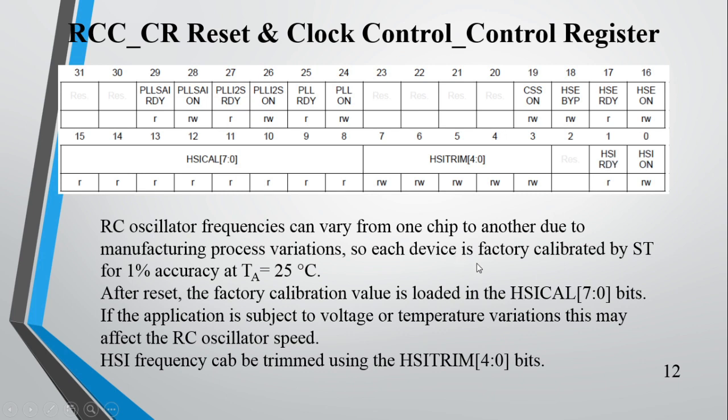So each device is factory calibrated by ST for 1% accuracy at 25 degrees Celsius. So it is factory calibrated. That calibration value is written in the ST microcontroller itself. And at the time of reset, what will happen?